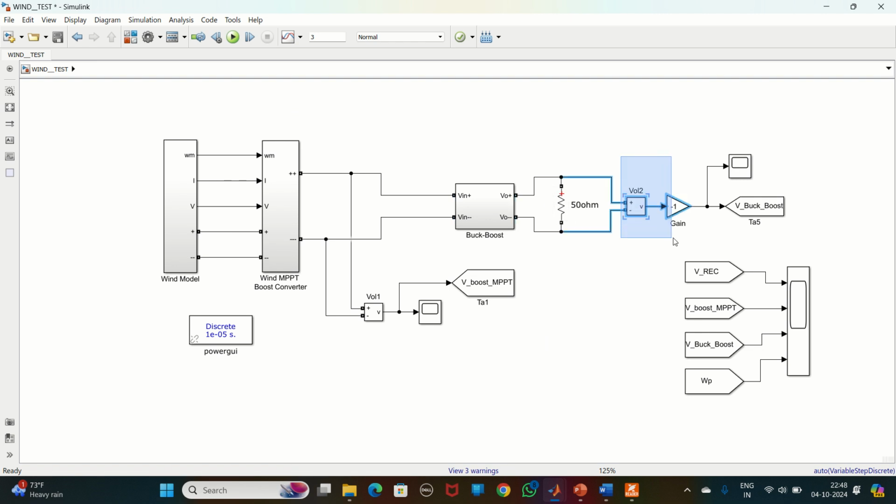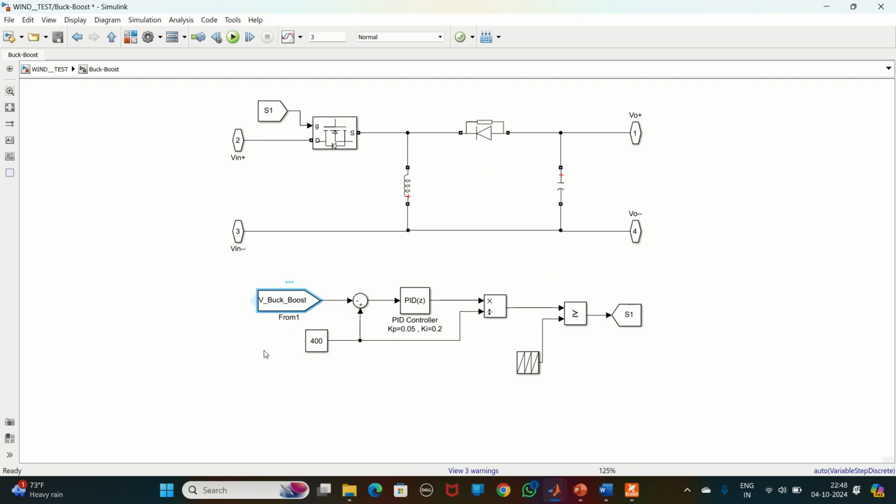Here mostly you are going to make some mistake. You are going to get a negative voltage, since the plus you have to connect here, and the minus you have to connect here. If you are not going to do it like that, then place a -1 here. Then, whatever may be the buck boost converter problem, the main second thing is that here you give one tag and there you take another tag, and you should not do that.